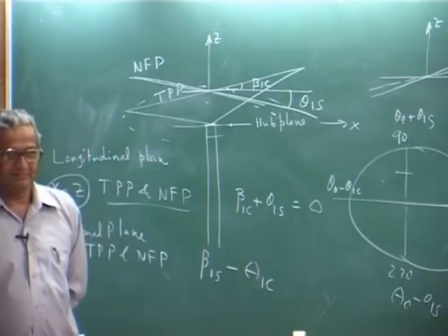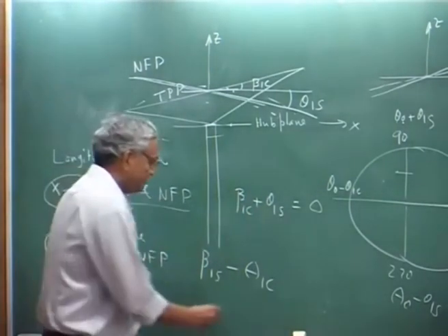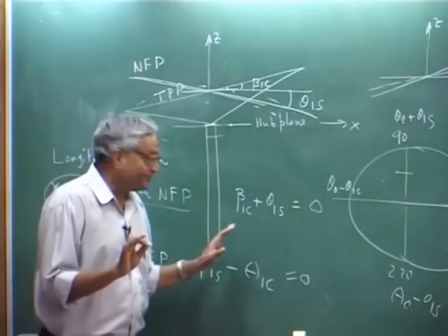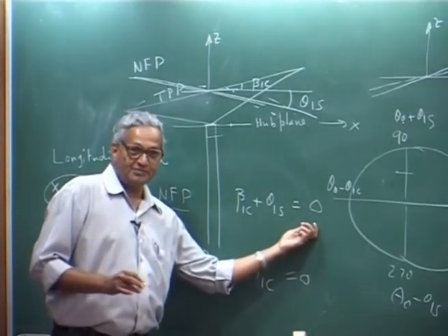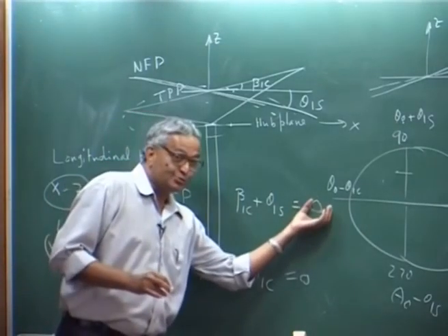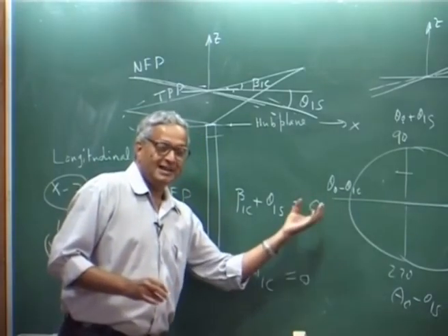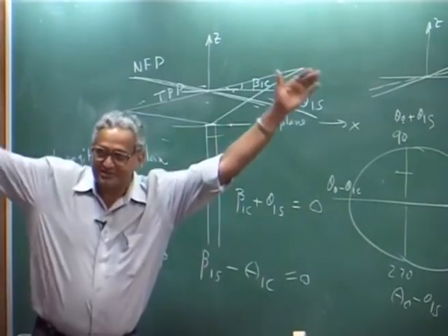Okay. Now, this is also 0 for hover, but please understand, in forward flight they will not be 0. In forward flight you will have some value sitting there, and that is a function of forward speed and how much the rotor disk loading is.